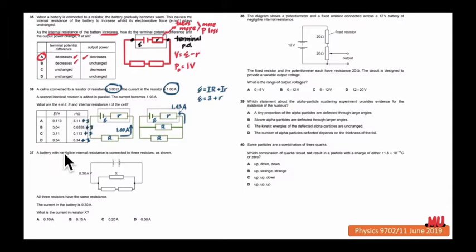Note, guys, that I am only looking at the figures. Do not be confused with the units, as this is supposed to be 1.00 A multiplied by R, and this 3 has unit volt. So we cannot do elimination here. Let's proceed and use the second diagram. The reciprocal of the combined resistance is 1 over R plus 1 over R, where R is 3.00 ohms. Combined resistance therefore is 1.50 ohms.